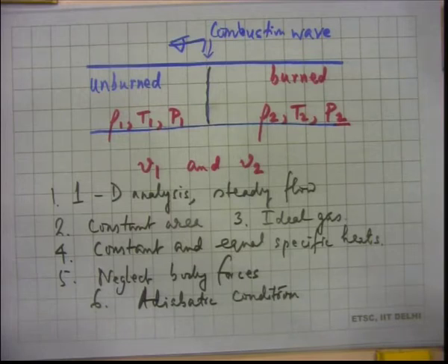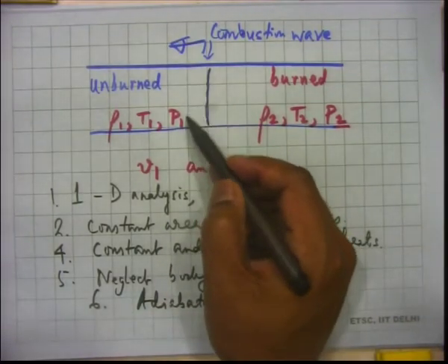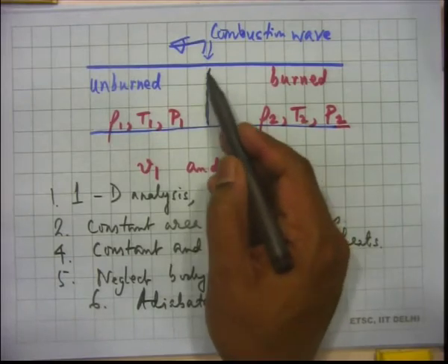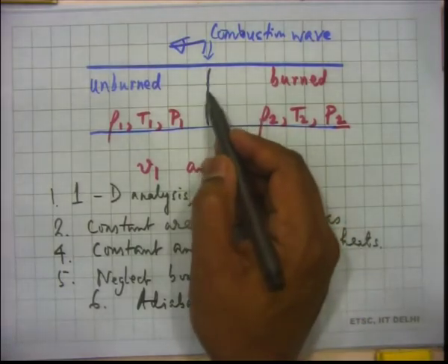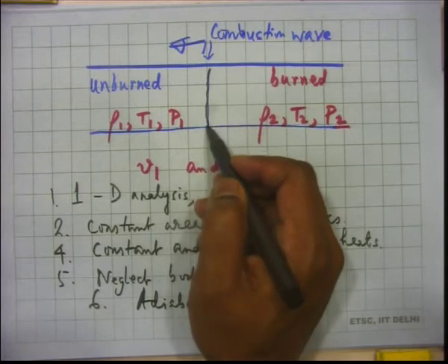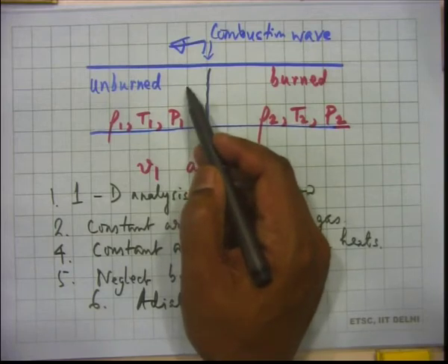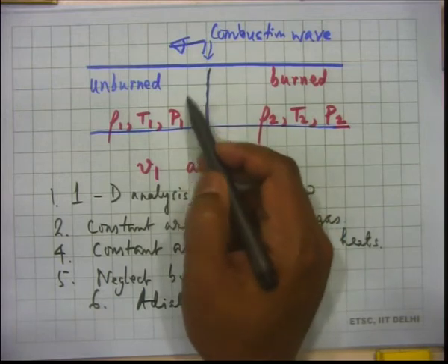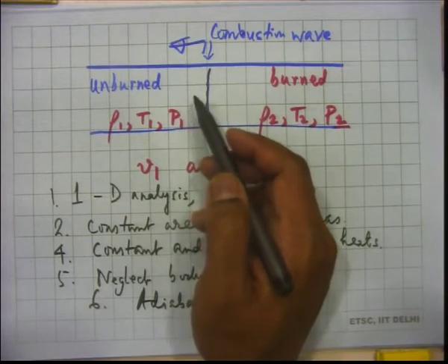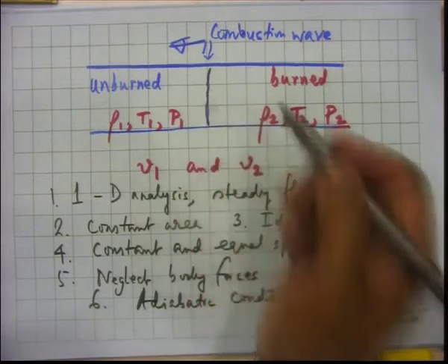Now, is this a collection of some material particles? So, if it moves from here to somewhere over here, do we say that the same particles have moved from here to here? No. So, the answer to that is no, because what has happened is at this point of time particles here were reacting, fuel and oxygen molecules were reacting. Around here now a new set of particles are reacting, because these have already burnt. These have already burnt, and then the combustion wave has moved here, and then some new set of particles are burning. So, this is like a wave. These are not material particles as such, this is a wave. So, this wave has moved. So, we call this a combustion wave.